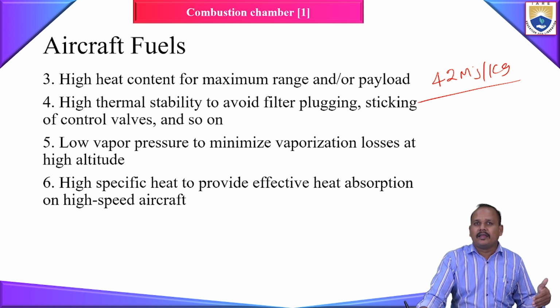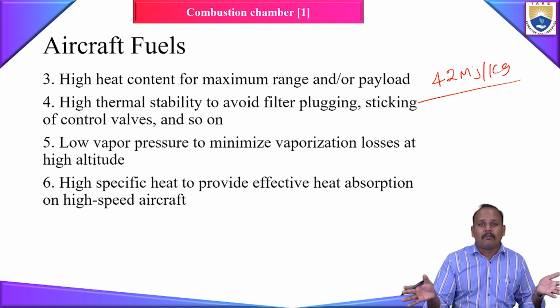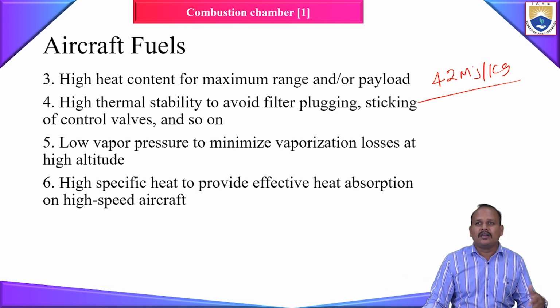If the heat content value of my fuel is less, what does that mean? I need to store more fuel if I want to increase my range or payload. If the heat content is less, your payload will be reduced, because mostly you will be carrying fuel alone and your aircraft is going to simply fly. So if you want to increase the range and the payload, you have to select a fuel which has a high heat content. And next, the fuel should have high